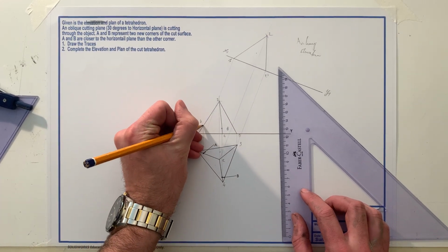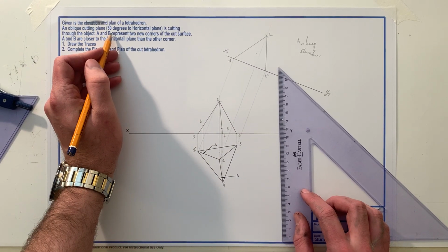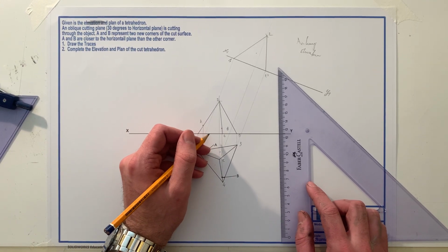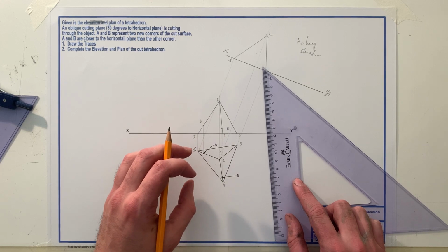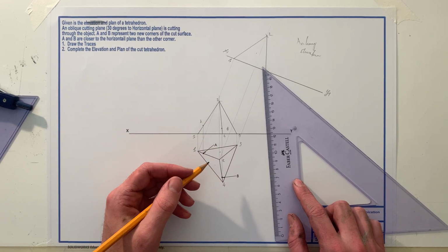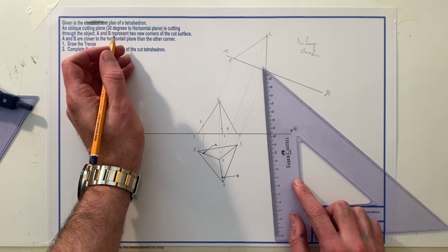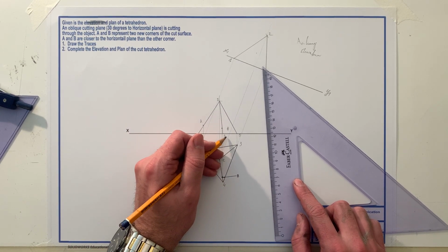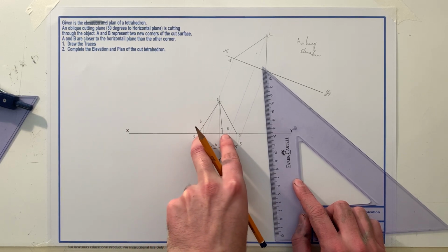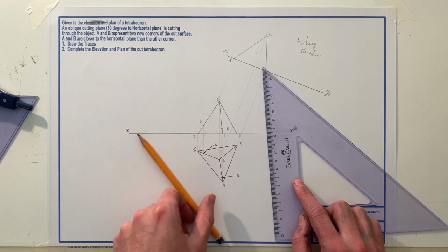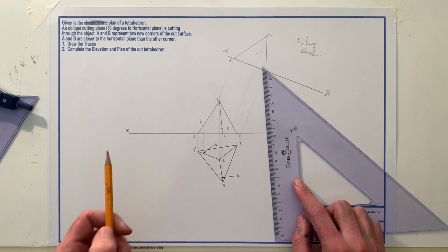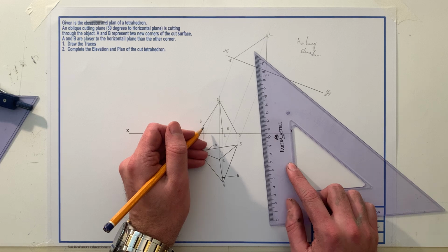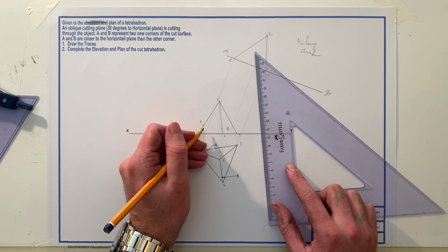So now that I have A and B, I can use my 30 degrees here and construct a cone. The cone provides a surface that my cutting plane is going to be lying against, because we know the cutting plane is at 30 degrees. We also know that it hits at these 2 points. So if I construct a cone here and a cone here, I can use the base circles of them down here in my plan to draw a tangential line to find my vertical trace. This construction was actually used before, when you were doing your internal and external tangential planes to a cone and a sphere.